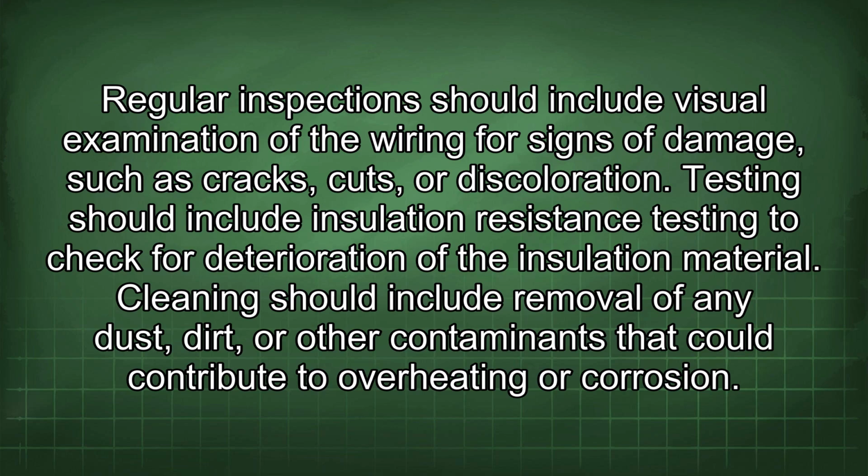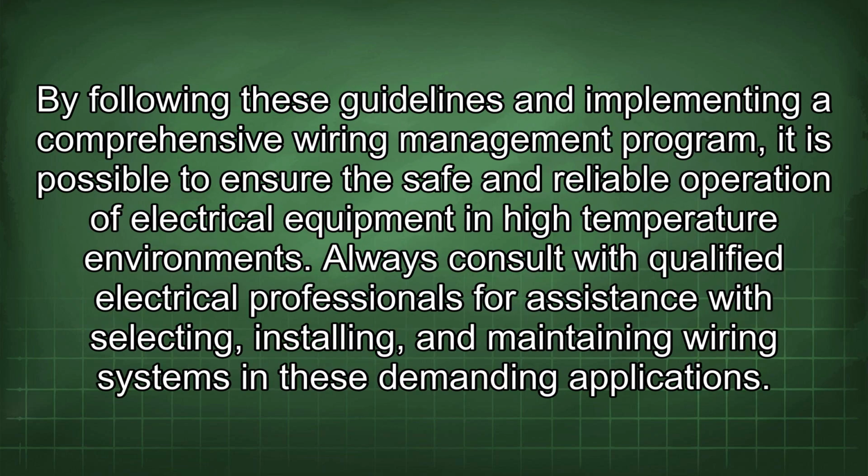Testing should include insulation resistance testing to check for deterioration of the insulation material. Cleaning should include removal of any dust, dirt, or other contaminants that could contribute to overheating or corrosion. By following these guidelines and implementing a comprehensive wiring management program, it is possible to ensure the safe and reliable operation of electrical equipment in high-temperature environments. Always consult with qualified electrical professionals for assistance with selecting, installing, and maintaining wiring systems in these demanding applications.